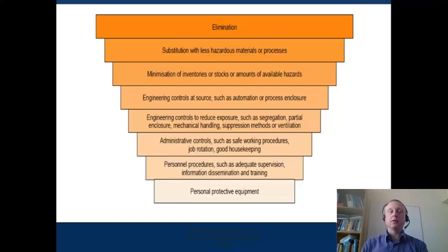And so wherever possible, you should have either difficult to remove guards or engineering controls which involve the halting of the electric current to the machinery, in order to stop that machinery from operating if the guard is removed. For instance, if you need to enter the enclosure in order to do work on the machinery.